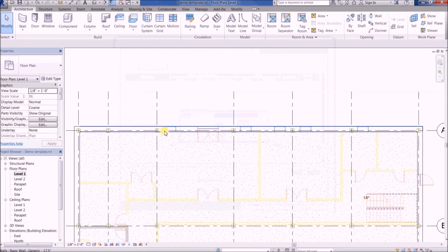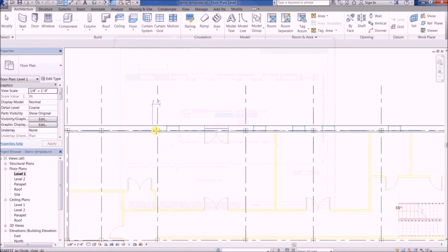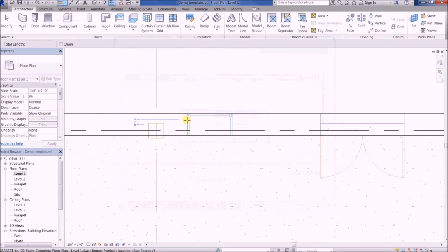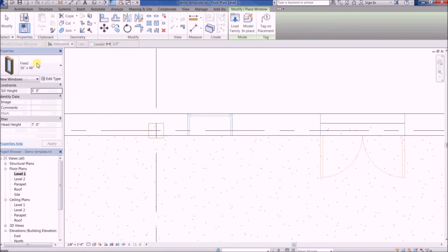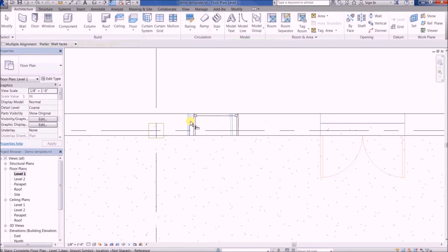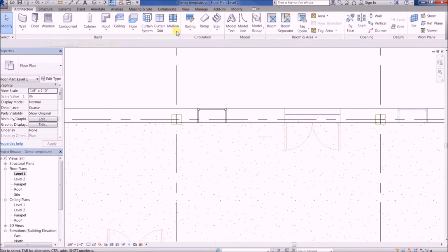Now we can see through our Revit walls and we can put windows in there. So I'm going to measure that window. Okay, we can't really see the height from a 2D drawing, but we could get that from another elevation or our AutoCAD file. So that's 3 feet wide. We could put a window in here that's 3 feet wide. Same thing, I'm just going to place it in. I'll align it later. It automatically cuts the wall, puts it in there.